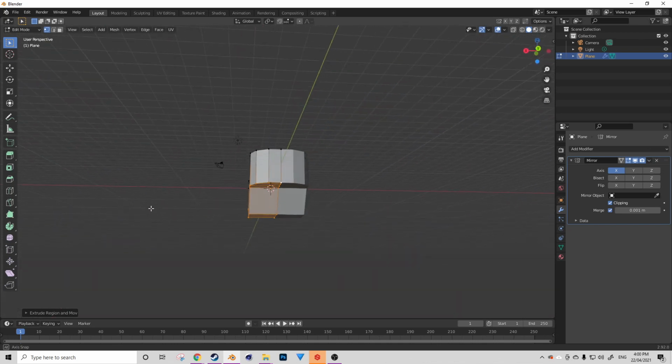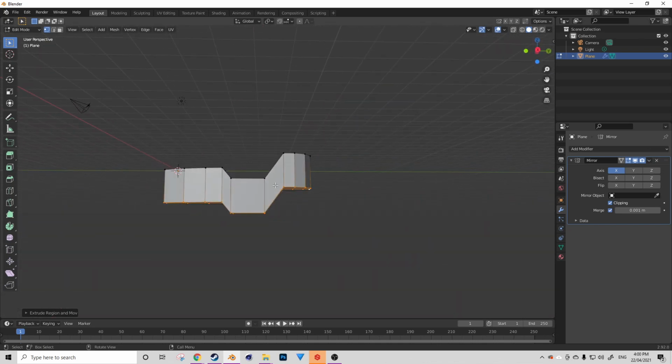We're going to essentially use a property of scaling because scaling is essentially multiplying. So we're going to scale on Z by 0. The reason that this function works is because scaling objects or scaling parts of objects in Blender works almost like a multiplication function. So if we think about it, if we scale 2 points from a median point here, if we scale it by 0, so multiplying by 0, we're changing those points' values to equal 0 because any value multiplied by 0 equals 0.